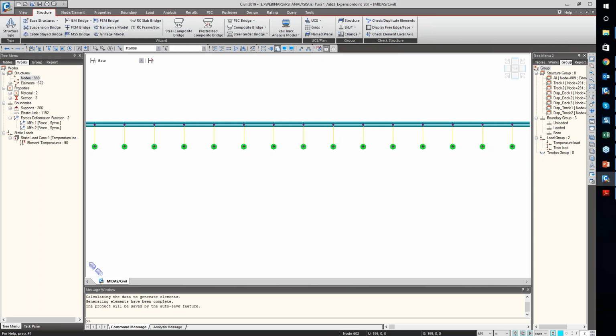For slab track on viaduct, for example in metros, CWR is carried out throughout. However, the largest rail stresses are generally found at the longest span. Yeah, that is true. For the longest span, we'll get more rail stresses.